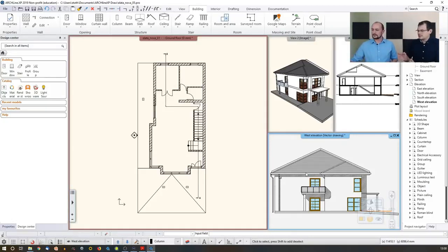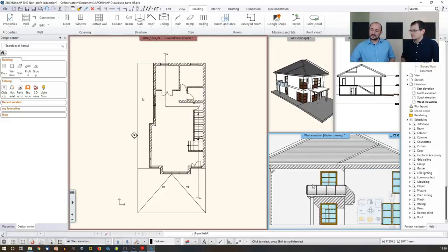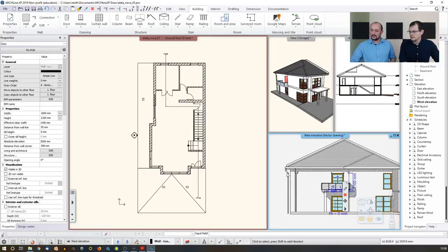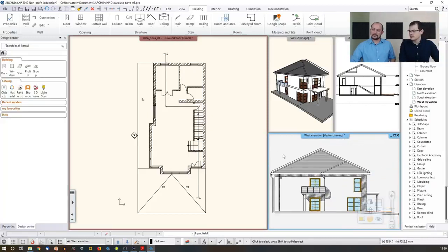Just a quick recap, this drawing is still in direct connection with the model, right? Yeah, so actually, when I click here, I see a line drawing, but it really generates a 2D view. I mean a line representation of the door, of the balcony railing that we have designed, and, for example, the gutters and everything else. So whenever the design changes, for example, we move the partition walls or change the doors to something else, then the same way we updated the section, we can also update the elevation.